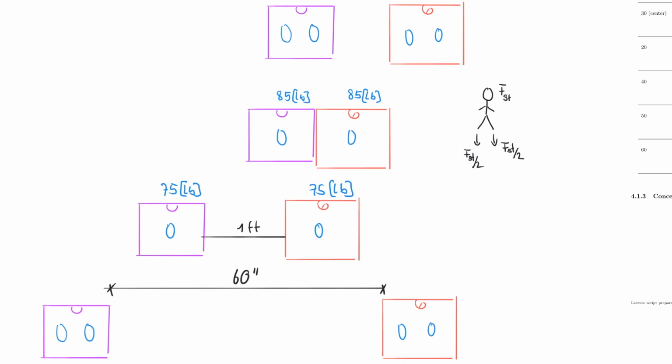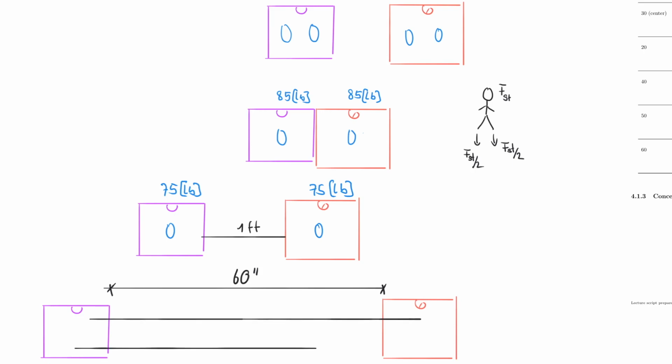But I say, no, don't worry. We can actually make this work, because I then usually bring in a rigid body, and the rigid body comes in the form of a wooden beam that I put on the scales. So let's draw the wooden beam on here. That looks something like this from the top. And I use some spreader beams underneath it to make sure that the load is properly introduced into the scale so that we can get accurate readings.